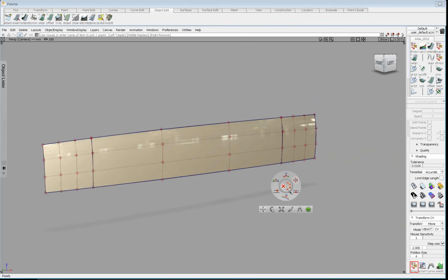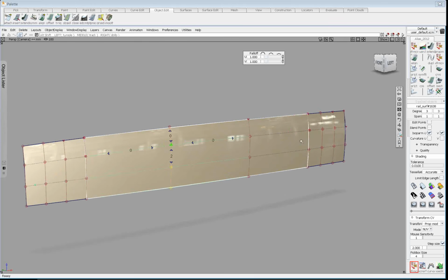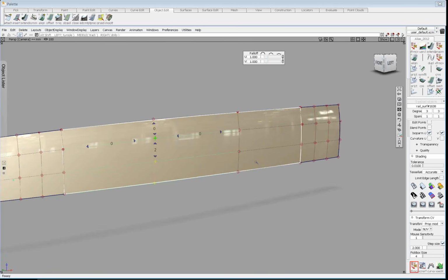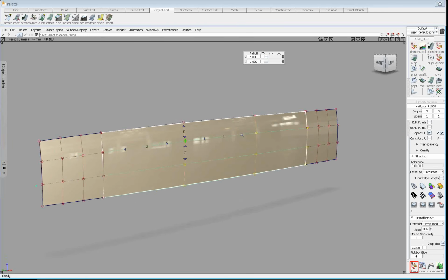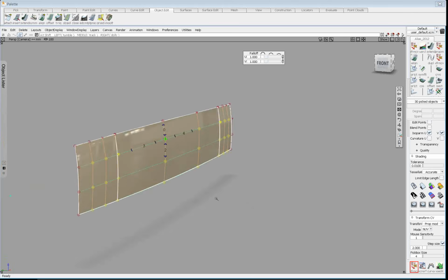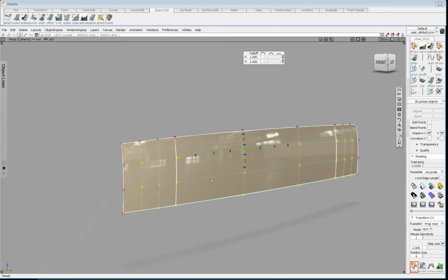So here I'm going to go to the prop mod and select this as my primary. If this had been flipped between U or V, it wouldn't make any difference as far as being able to extend the proportional modification. I hope I'm reading the question correctly, because I know some people have asked in the past, well, if this is going in the V direction and that's going in the U direction, are they going to be able to? Yeah, you'll still be able to continue to make your modifications across the boundaries.